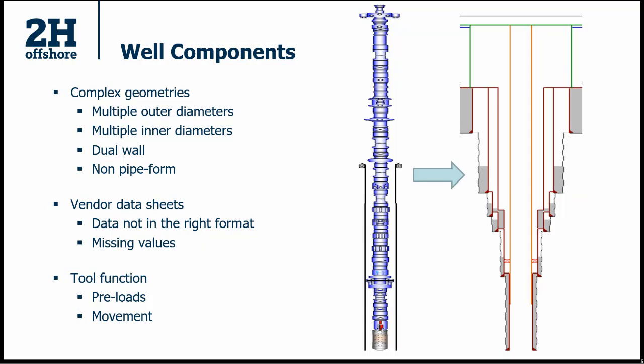There's a certain number of unknowns which are going on. So it's a relatively high risk stage of a well's life. Now we're expected to verify that as a primary barrier. And what we see is when we do the analysis, we put it in our tubular design package and we get the schematic on the right. And quite often we see it as just a section of tubing with a packer on the end. And the question is, is that sufficient? Is it accurate enough?